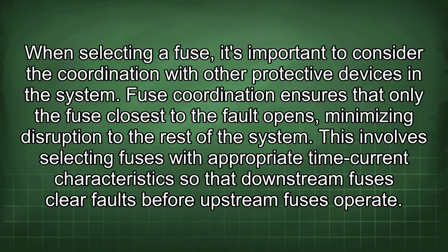Fuse coordination ensures that only the fuse closest to the fault opens, minimizing disruption to the rest of the system. This involves selecting fuses with appropriate time current characteristics so that downstream fuses clear faults before upstream fuses operate.